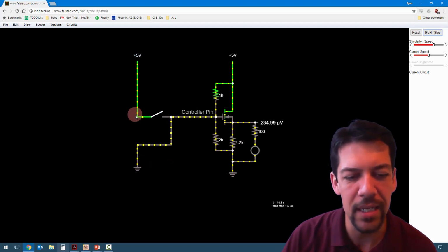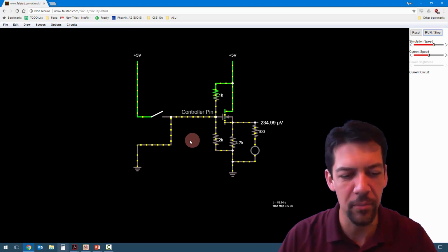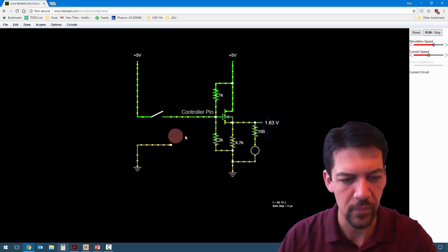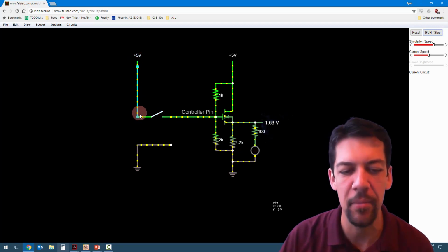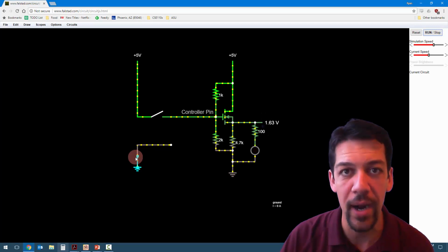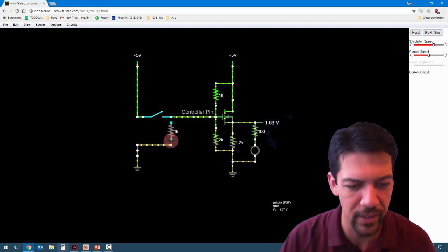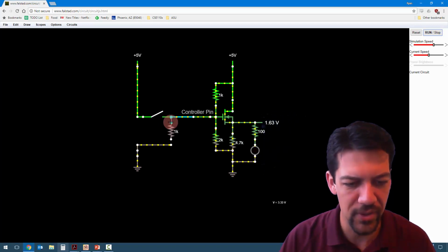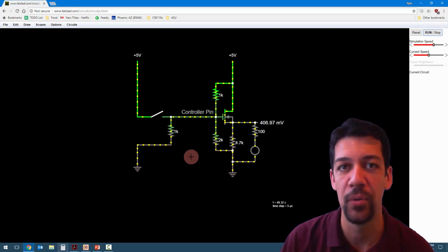So what we really need is something to limit the amount of current that flows in between 5 volts and ground when the switch is closed. So we know what that is. That's a resistor, and that's a really simple little thing to just drop into my circuit here. So I added my resistor, I'm gonna hook it up, and now I get the best of both worlds, right?